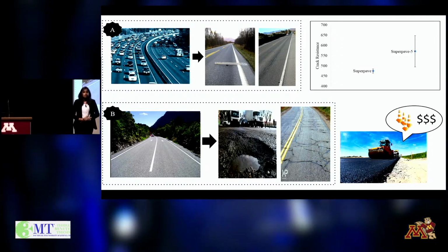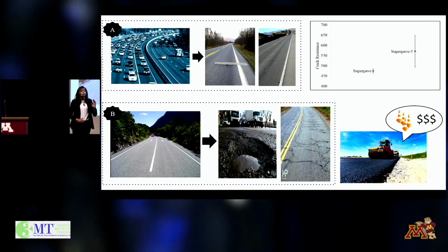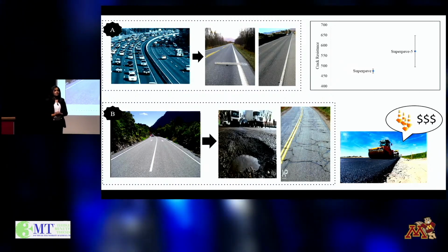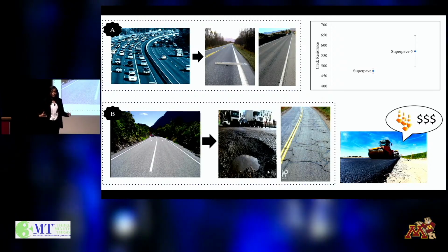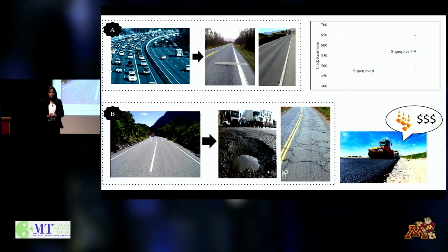Therefore, for our research, we adopted the Superpave 5 mix design methodology. That is, we produced asphalt mixtures with 5% air content. These mixes are quite dense by themselves and do not require much further densification. They protect the pavement from failure due to weather changes and the low densification factor.